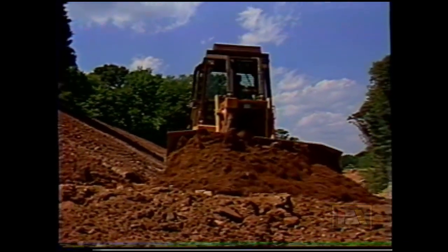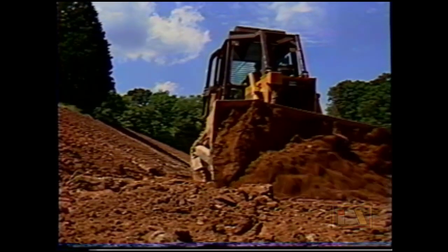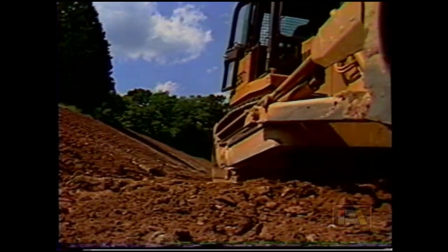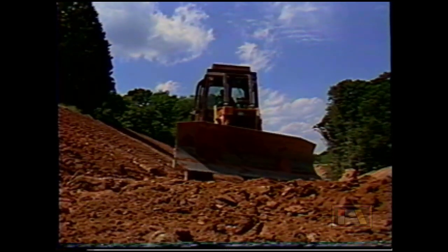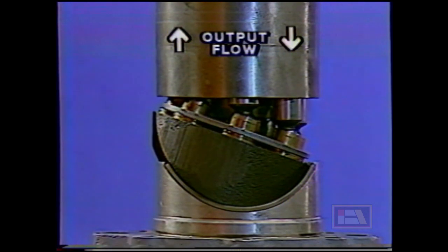Many hydrostatic systems are designed to operate in a forward or reverse direction. In order to reverse the direction, all the pump has to do is reverse the direction of flow to the motors. It does that by simply changing the angle of the swash plate across center, thus changing the direction of output flow.